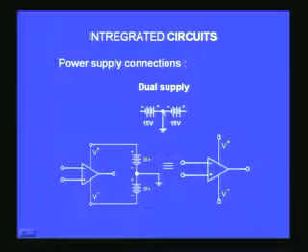So if you now look at this end of one of the batteries, this is grounded, that means the negative is grounded, and therefore it becomes a plus supply, plus with reference to ground. If you look at the other side, you find the plus end of this battery is connected to ground, and therefore what you get is a minus supply with reference to ground.